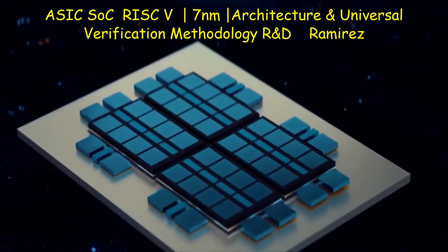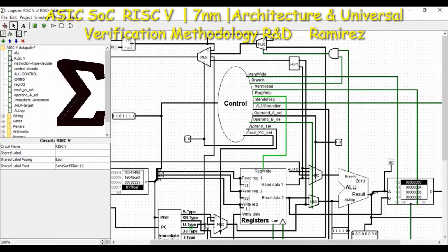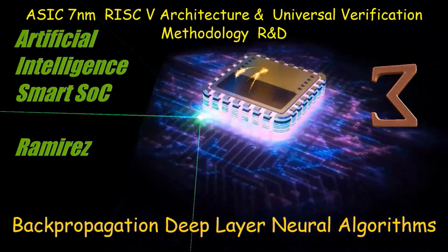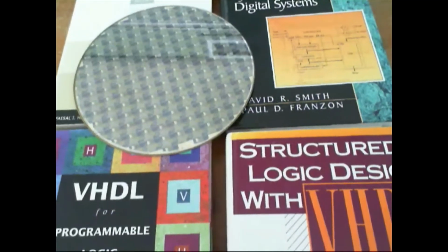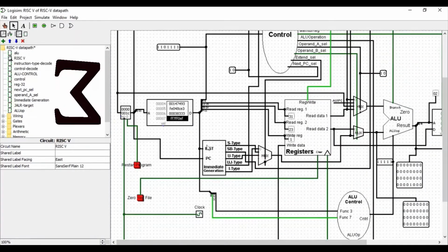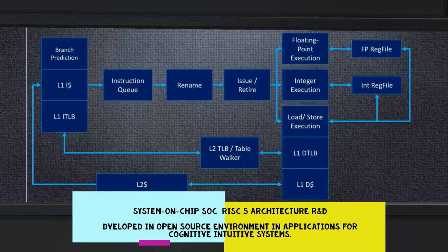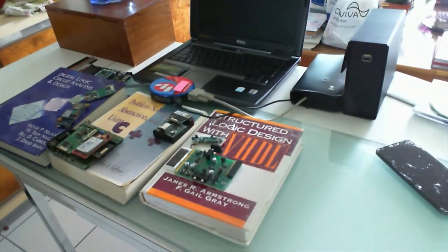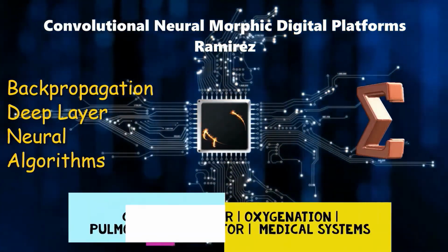The high-level system design process applied in this design was as follows. First, I identified the system requirements, followed by writing the preliminary specifications and parameters, thus developing high-level algorithmic models in both C and C++ and also in VHDL. After that, I refined and tested the algorithms and determined the hardware and software partitioning at a system high level.